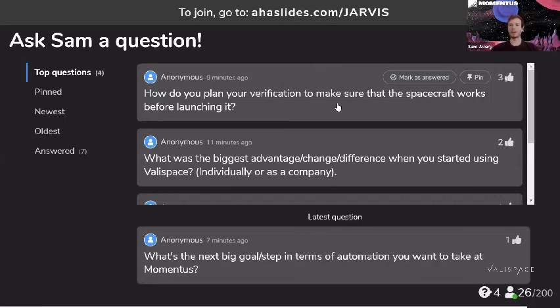each requirement. So if there's a requirement that, say, we need to avoid a death mode of the spacecraft, which means that you issue a command and it kills the spacecraft, that requirement then has, say, an analysis, a test, and maybe an inspection or review or something. And those will be throughout the process. So maybe at critical design review, we have a review stage. We have a test that we do at, say, during the assembly, integration and test process. So that's generally how we do it.